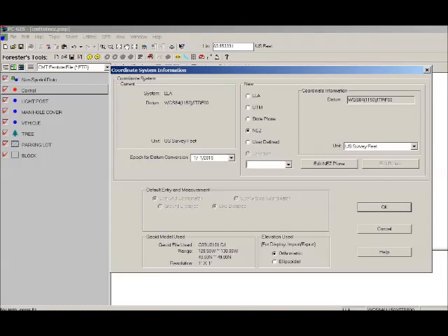If you would like to place the elements of a CAD design in a PC-GIS job, then you could ask for the shapefiles, or the DXF output file, of the drawing. As the DXF output of older CAD software does not contain coordinate system information, you will need to set up a local and easy coordinate system for importing the DXF file.